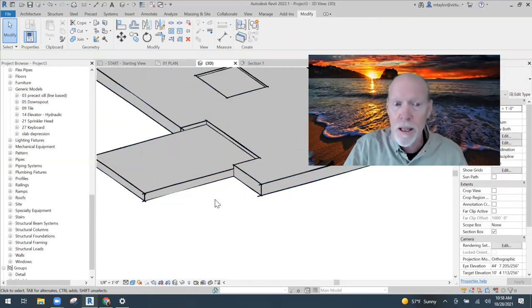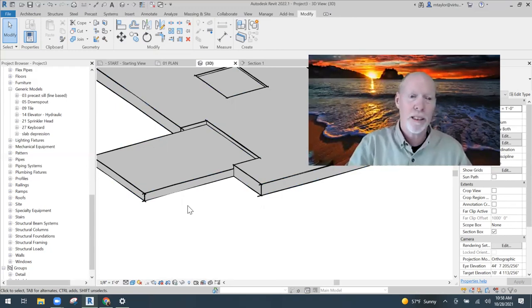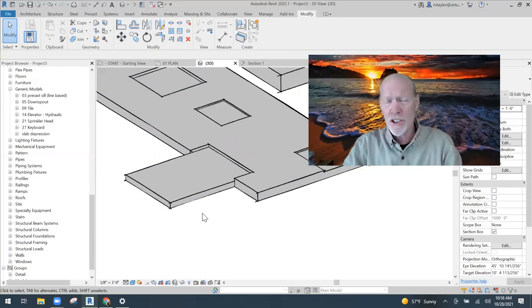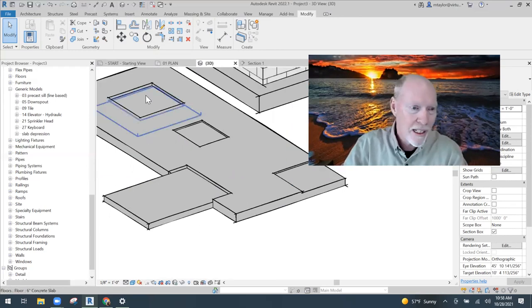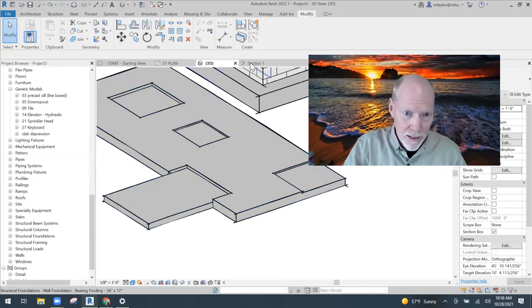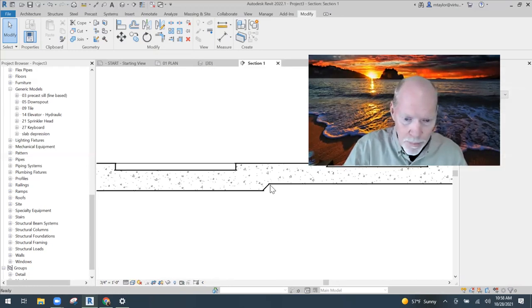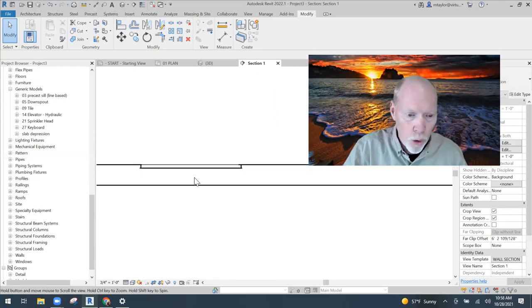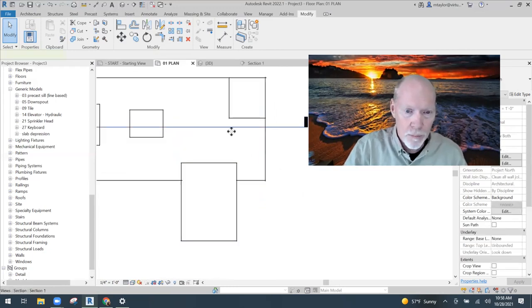It's cutting back in, possibly where a door is, or so that you can have water not come into your building at this location. I'm just showing you the different ways that we can deal with this. So a slab depression, we can either put in a piece of slab and extend it past, go back to my section. So it's looking like this, extend it past and put the little cants on it. Or we can flush it out at the bottom by putting 2 different slabs. We can, wait for it, put it on the edge.